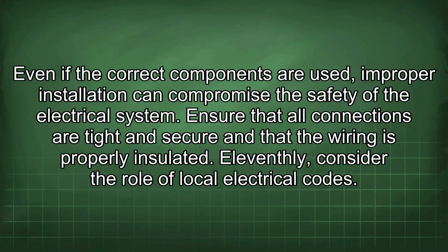Tenthly, keep in mind the importance of proper installation. Even if the correct components are used, improper installation can compromise the safety of the electrical system. Ensure that all connections are tight and secure and that the wiring is properly insulated.